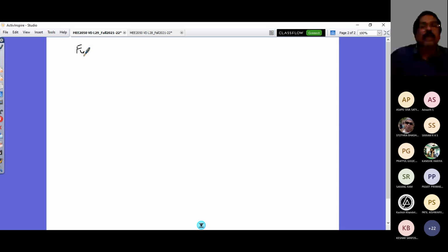It is given by C alpha into alpha, per axle. This axle can be the front axle or the rear axle. So I take one axle, and Fy is C alpha into alpha minus C gamma into gamma. Why this minus? It's a vectorial addition, and we have seen that the directions are opposite. So that comes like this, and let us say this is equation 1.